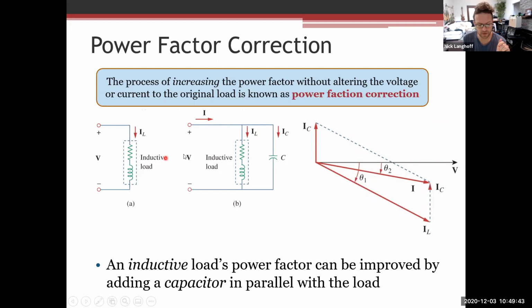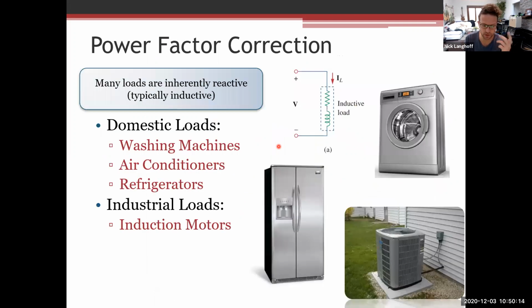If it's primarily an inductive load, adding some capacitance in parallel actually can help. Inductors are going to have a positive reactive power. Capacitors are going to introduce a negative reactance, and that can actually bring the voltage and current waveforms closer to in phase, and in fact increase the energy efficiency of your device. So when you see on modern devices today an Energy Star efficiency marking,